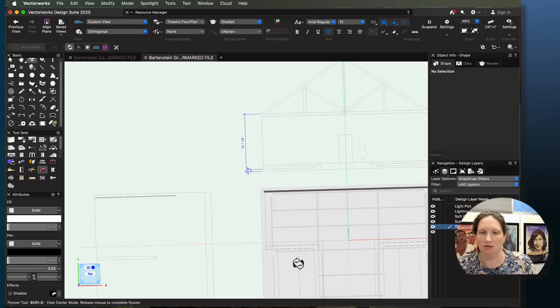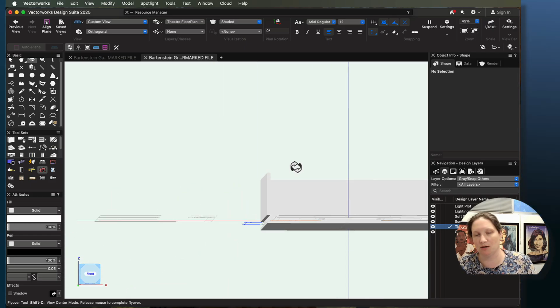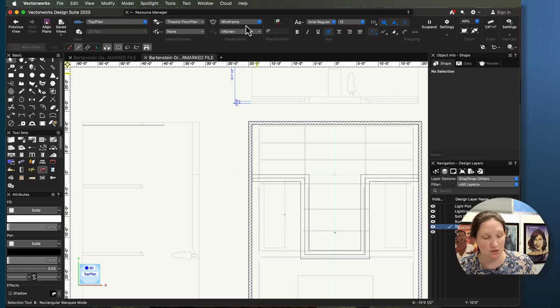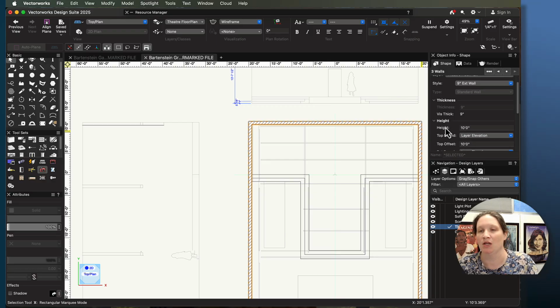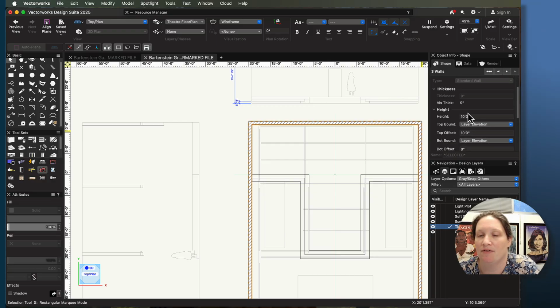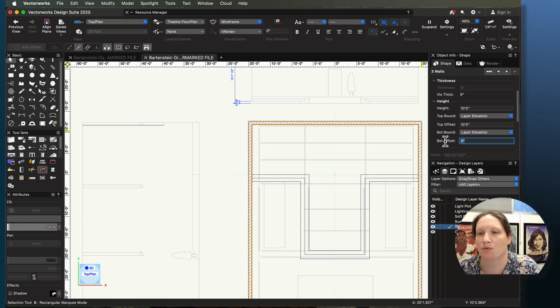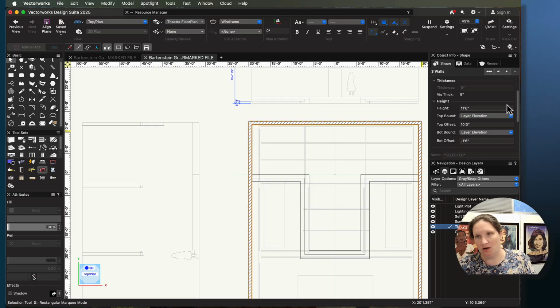You'll notice, there they are, but they're floating. Oh no, they're floating above the floor. There is an awkward gap. So let's adjust these walls now to go down to the very bottom of the floor and not just float up in space, okay? So right now they have a height, they have a bottom offset, right? They have a top offset. So we're going to change our bottom offset to that -1 foot 6 inches, right? -1 foot 6 inches. That's going to move the bottom edge of the wall.